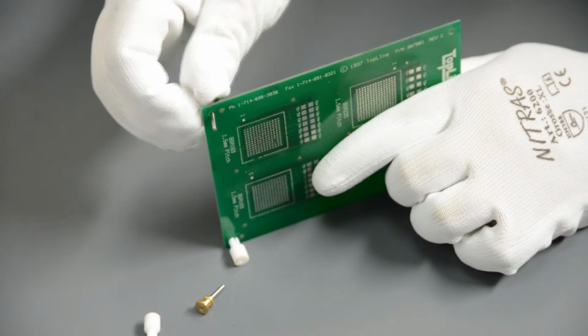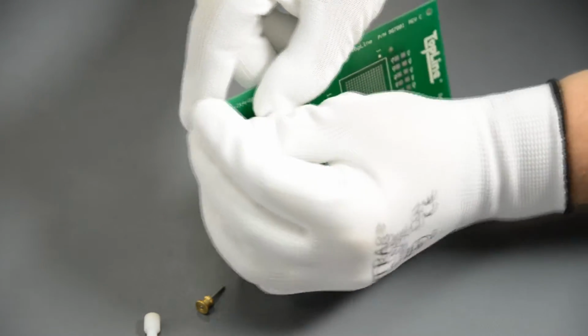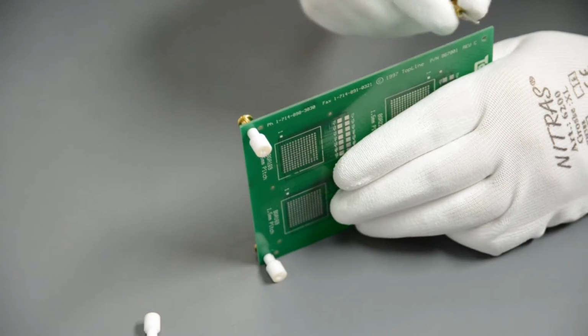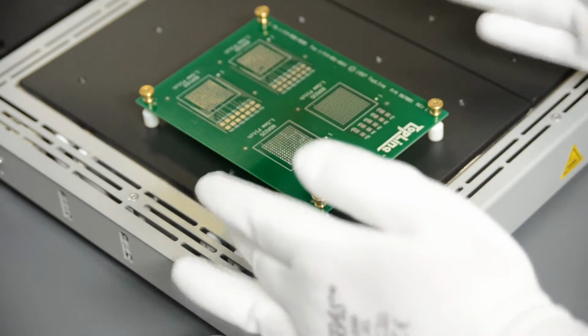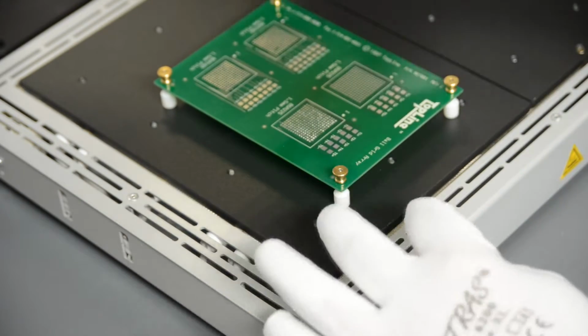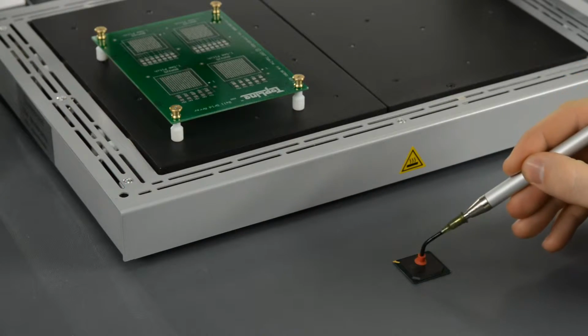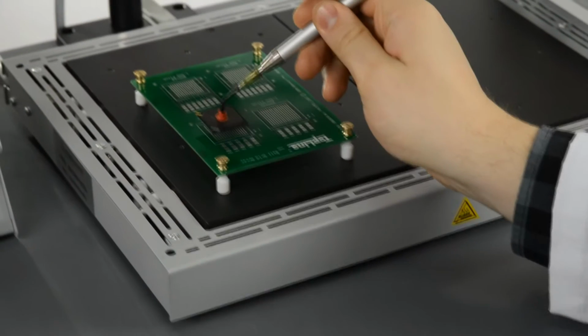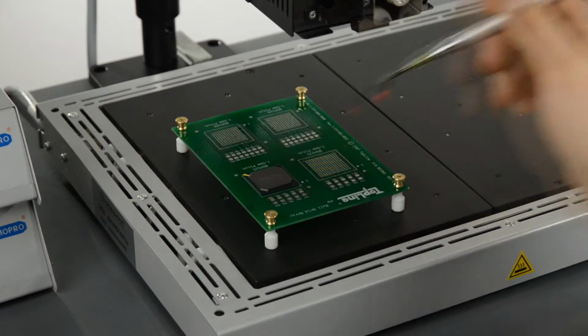Place the board you will process on the bottom heater plate with an optimal gap. Use the supplied fluoroplastic racks for that. Try to place the board in the center of the heating plate, which lets you keep equal temperature conditions across the board body and will prevent or at least minimize deformation. Place the processed component on the contact pads by the method accepted at your enterprise.